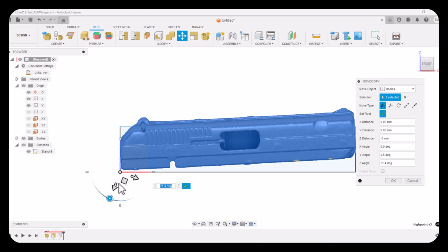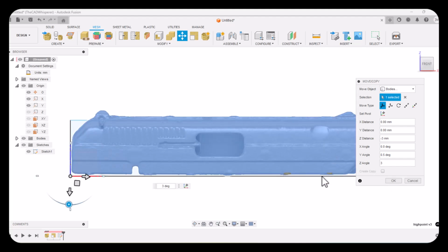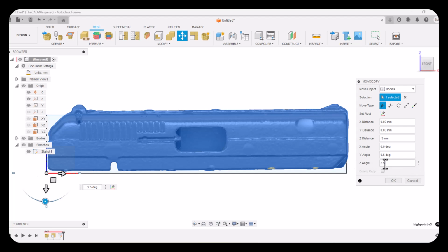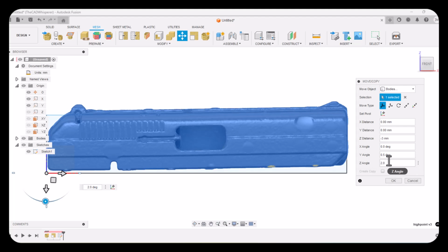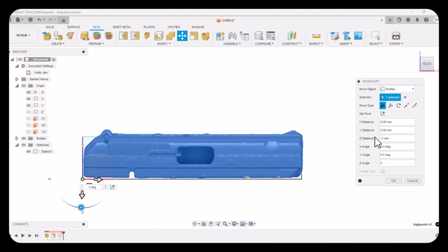And what I do there, I forgot to click done. So let's set that set point. Then don't forget to say done. Now we can rotate this, and we'll get it down some angle, and let's do 3 degrees. And that looks like maybe a little bit too much. Let's try 2.5. And I think I liked it better at 2 degrees or 3 degrees. Here we go.